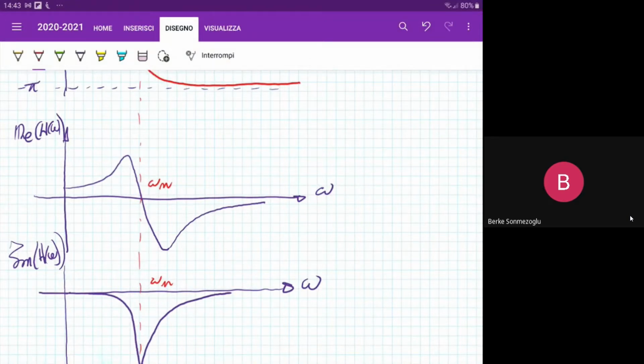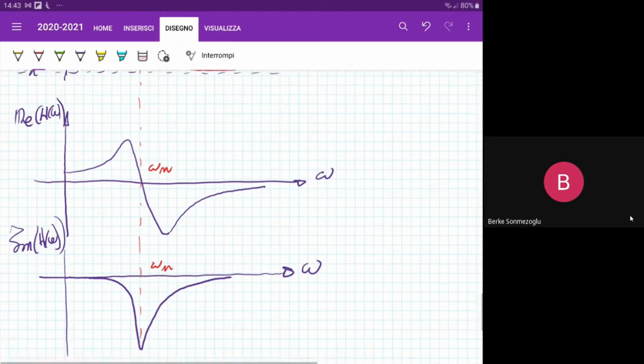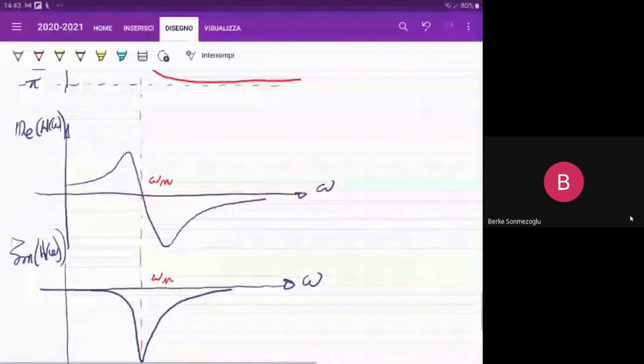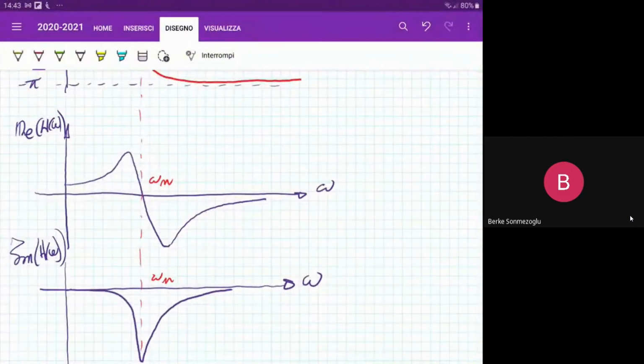Then at the crossing of the x-axis, the natural frequency, it is clear here that the system is reacting with an imaginary contribution only, and that is once again evidence of the quadrature condition. The response is purely imaginary. It is rotated at a half pi angle with respect to the input. They are orthogonal. Output and input are orthogonal.